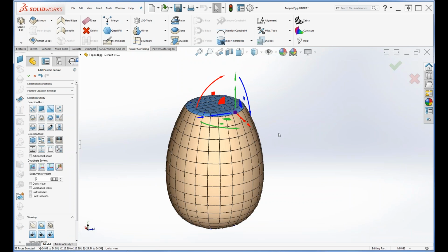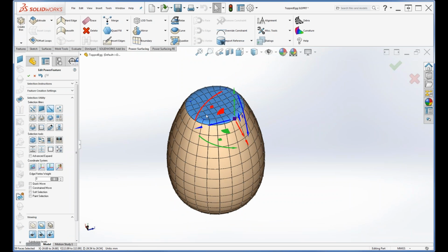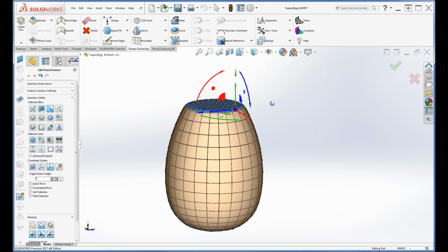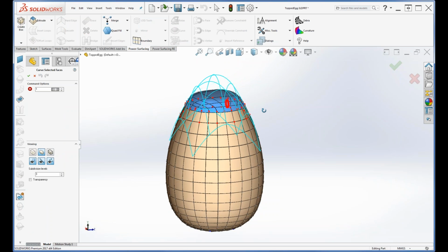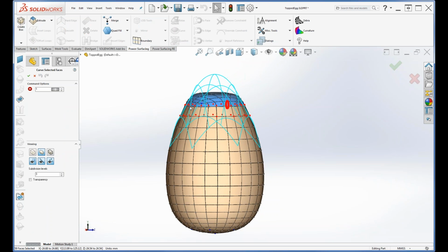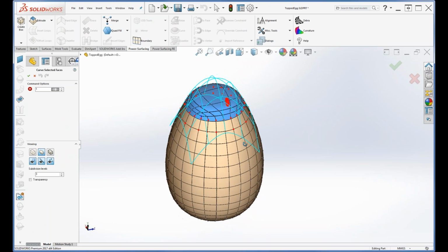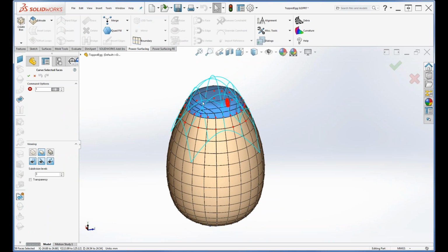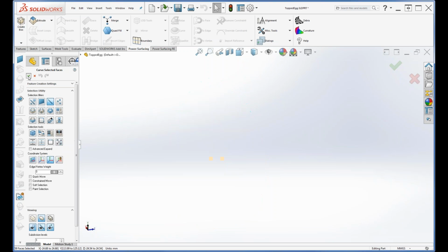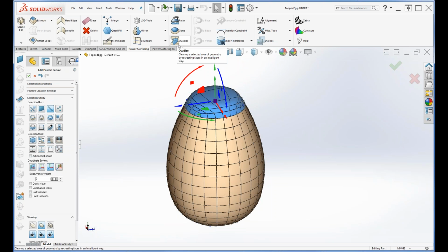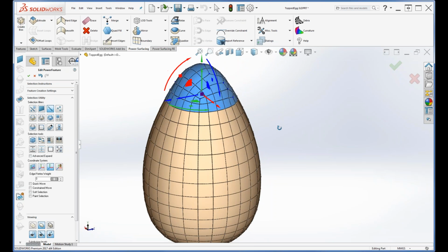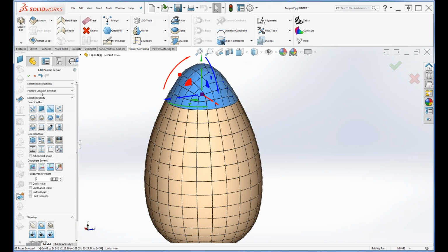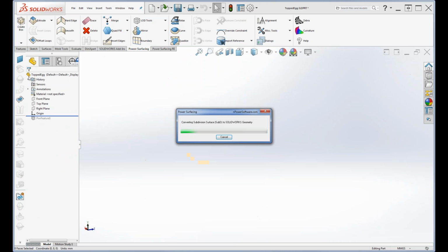But now if I click this, it automatically goes and adds all our topology there. I can use my curve tool on this. You can see it's trying to copy the curvature that it inherits from the first two rows out here, but it's not doing that well just because of the design of all the faces. But I can accept it as is, and one of our new really nice tools here is quadize, and it's going to go through and remodel this, and so it allows that curvature to come back up, which is a really nice thing. Okay, so that's a good one. We'll go ahead.